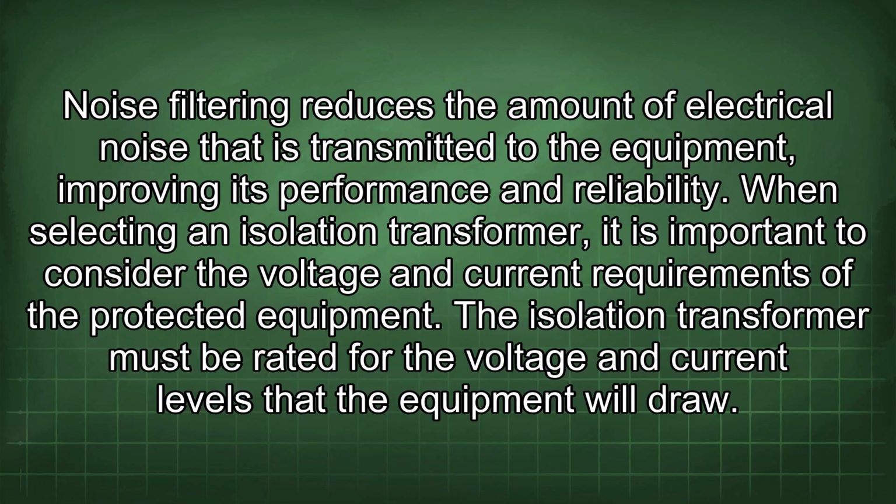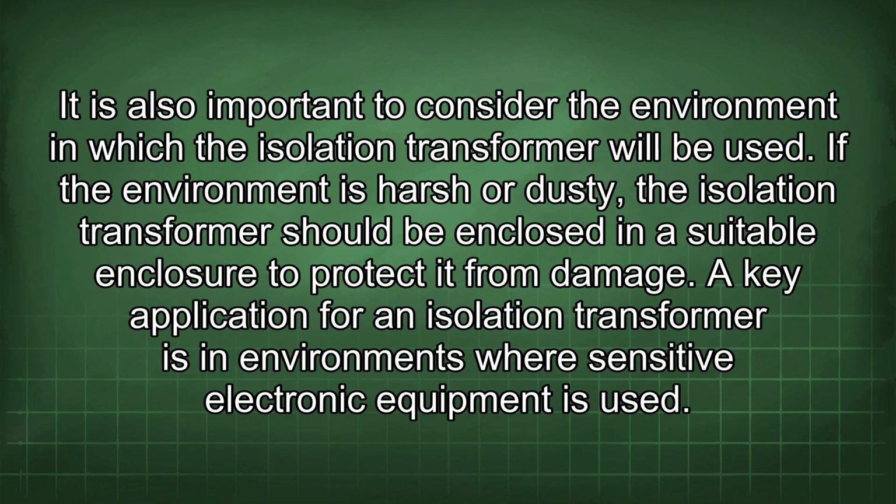When selecting an isolation transformer, it is important to consider the voltage and current requirements of the protected equipment. The isolation transformer must be rated for the voltage and current levels that the equipment will draw. It is also important to consider the environment in which the isolation transformer will be used. If the environment is harsh or dusty, the isolation transformer should be enclosed in a suitable enclosure to protect it from damage.